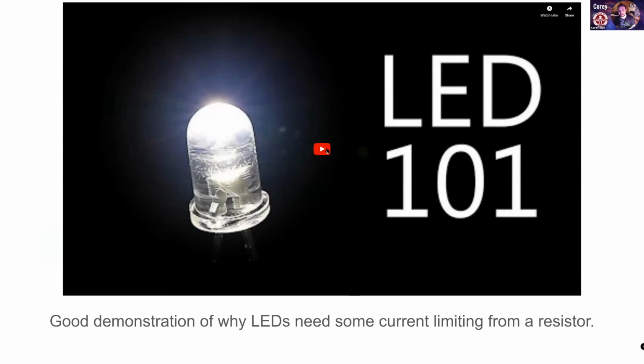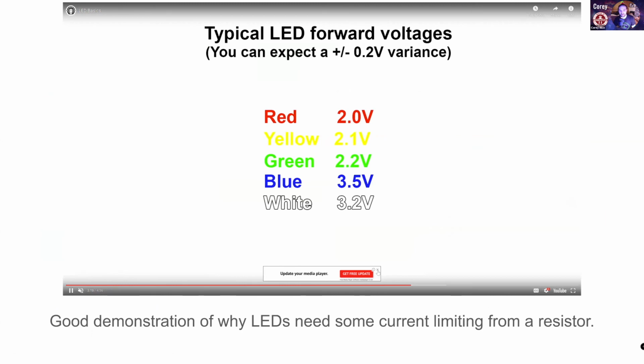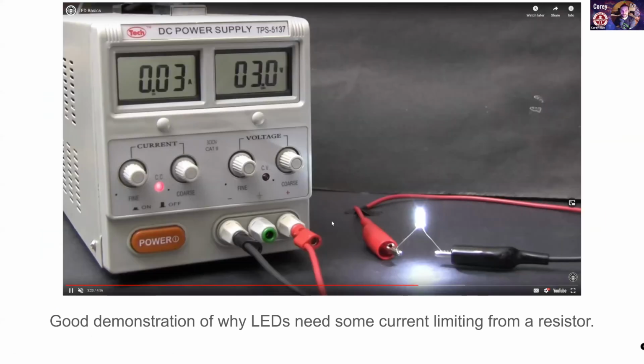I'm going to play it without sound, but with subscripts like we talked about, and then I'm just going to narrate it like we figured out worked last week. So these are typical forward voltage drops. And this is Afrotech Mods on YouTube. He's running an LED here with a constant current supply. So this power supply is only capping it at 30 milliamps or 0.03 amps and at 3 volts.